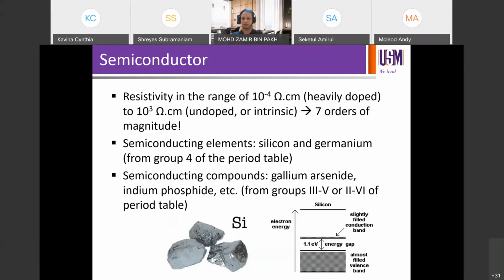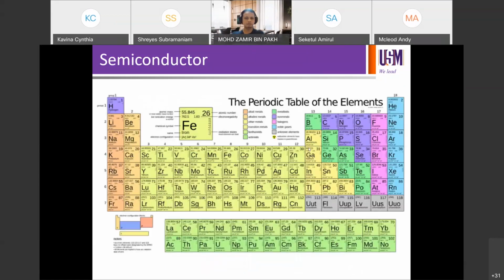So that makes the properties of the semiconductor in between insulator and conductor. These can in fact be tuned as well. So if you talk about germanium, the band gap is 0.7 eV. If you talk about silicon, then it's 1.1. If you talk about gallium arsenide, it's 1.4. Cadmium telluride, 1.4. Indium phosphide, 1.5. So you have a range of different band gaps for different applications. Okay, so that's the beauty of working on semiconductors. You can actually work across the spectrum according to what you actually need.